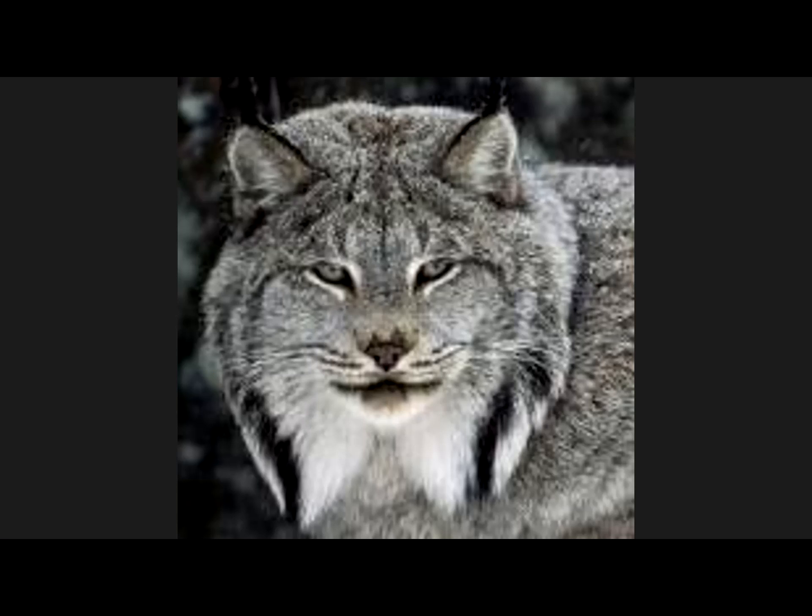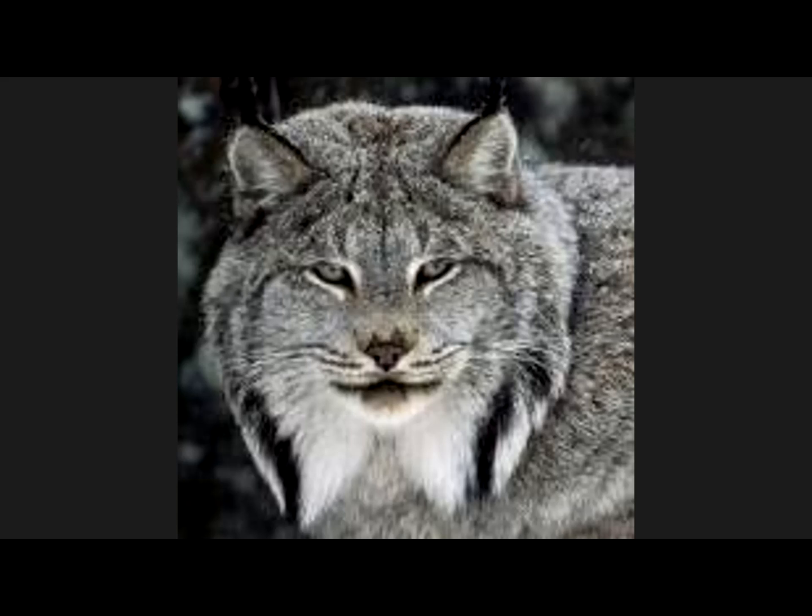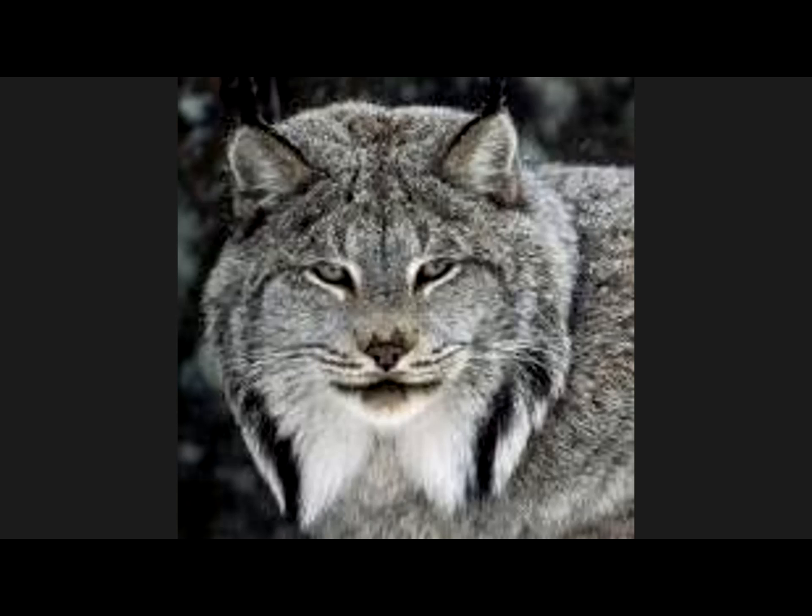That's right. And the cog has nothing to do anymore. It's out of work. It's been replaced by robots. But once you've activated the streamer and it's reading the LUT memory, it'll just all go on in the background, but you can tweak the values in your cog. Like your cog code could go back and poke the pin to change values, which is what you were doing, to change the timing. It could very easily have been doing something else entirely. Totally, yeah.